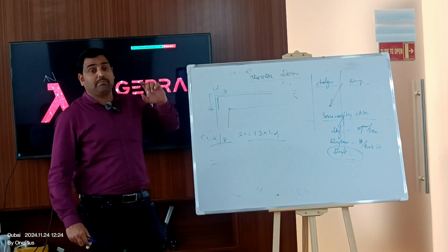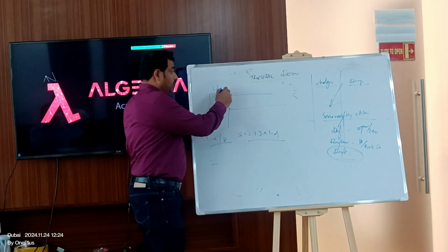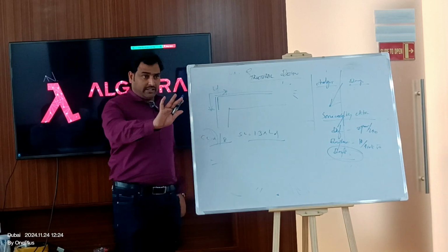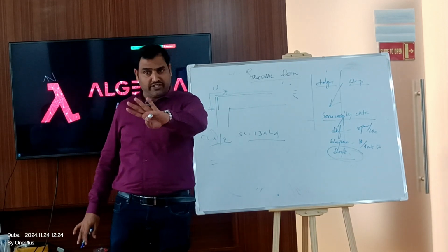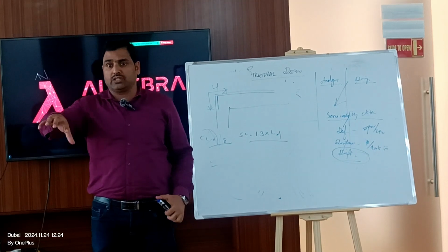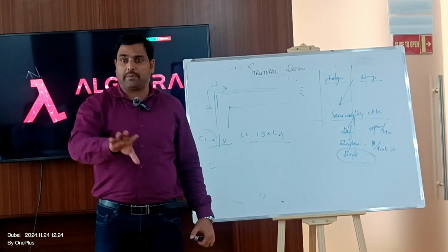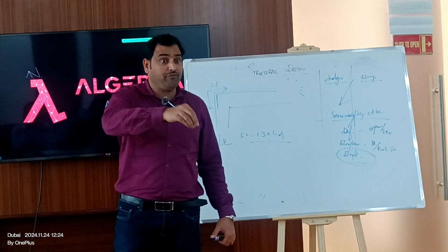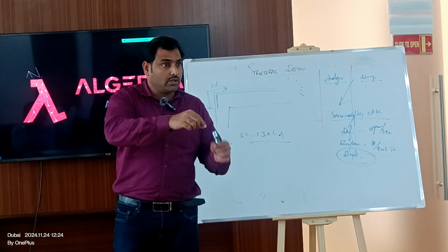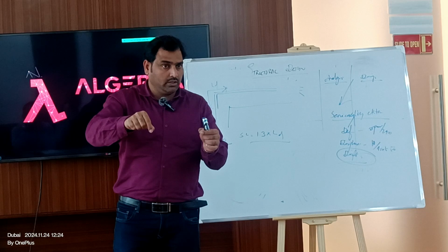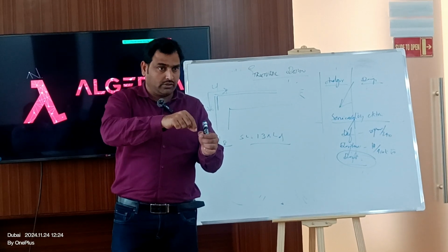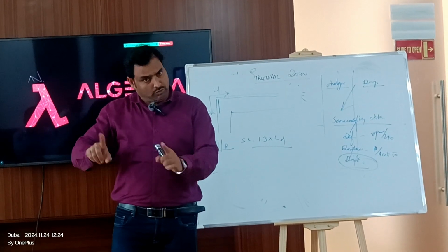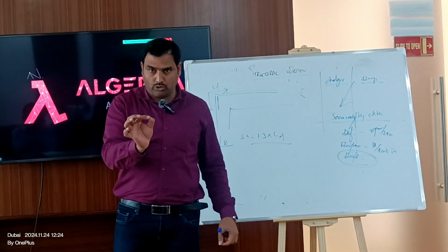So coming back to the development length question actually. What is the difference between A and B? See, the rebar is the same again. The yield strength, which is 460, 500, is the same, using the same rebar. If you are using 8mm diameter, it is also a deformed bar. What is 500, 550? It is a deformed bar yield strength. It is not with respect to the diameter of the rebar. Even if you are checking 10mm, you will get 500. If you are checking 12, you will also get 500. That is the minimum yield strength I am talking about.